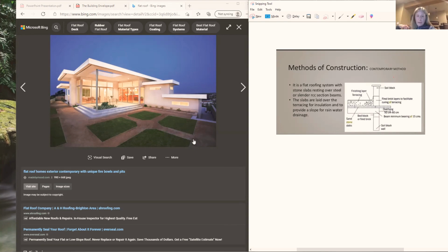So materials, the flat roofs, what I read was there's 3 different types of materials used for the flat roof. One is hot tar and gravel. One is single ply rolled roof, which is called modified bitumen. And then a rubber membrane is the third kind. The construction, she's got it there. Basically, what I read is it's a ceiling nailed to joists which support a deck. And then there's a waterproof vapor barrier, then insulation, and then whichever roof board material of the 3 I just mentioned.